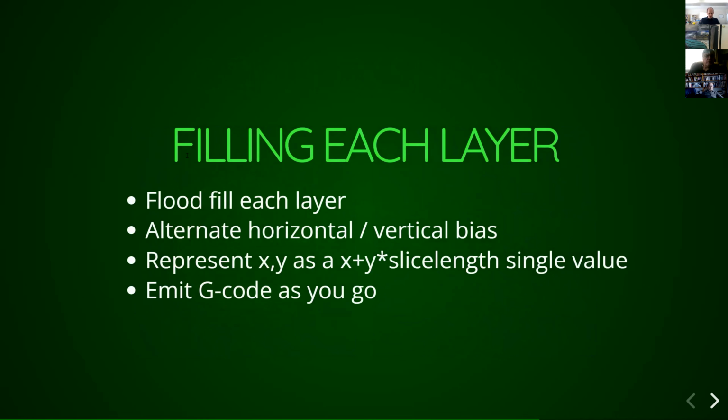You need to be able to flood fill each layer to figure out where to move the print head. Or rather, sorry, you need to do a plan for each layer. And to do that, I use a flood fill. And with 3D printing, you generally don't want to have your movements be aligned. You don't want a stack of horizontal lines covering each other because that won't have good structural strength.